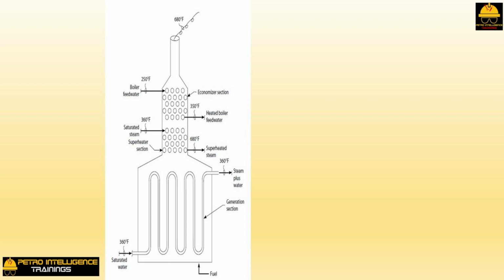In the economizer section, the effluent from the deaerator at 250 degrees Fahrenheit would be heated to 350 degrees Fahrenheit. As the specific heat of water is 1.0 BTU per pound degree F, we would need 100 BTU per pound of water. However, to produce 100,000 pounds of steam, we might need a 10% blowdown rate to control TDS. This means 110,000 pound/hour of boiler feed water is needed. Therefore, the economizer heat duty would be 110,000 pound/hour times 100 BTU per pound equals 11 million BTU per hour.